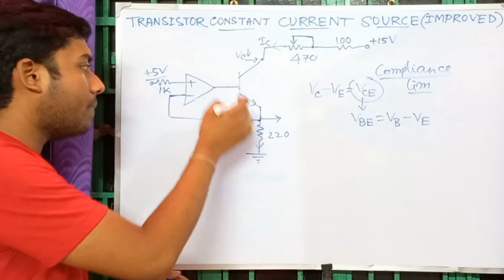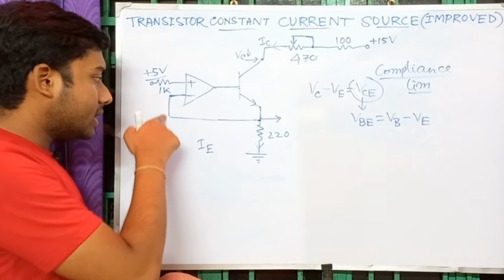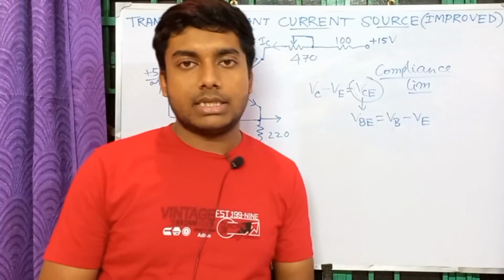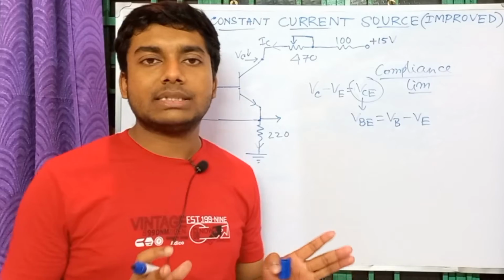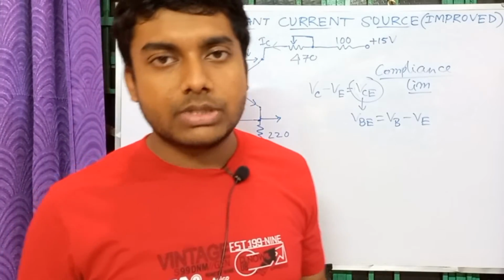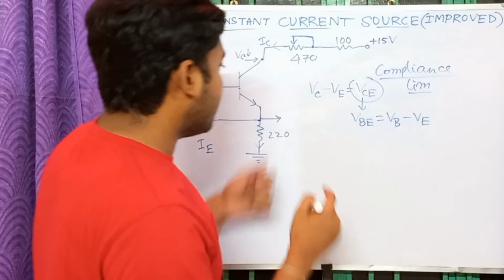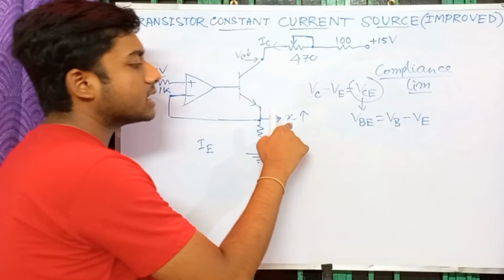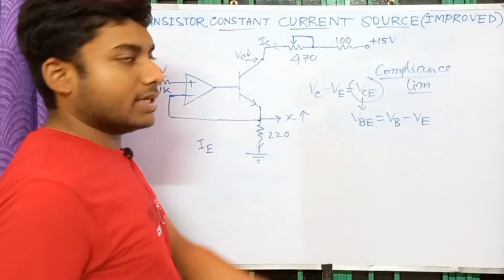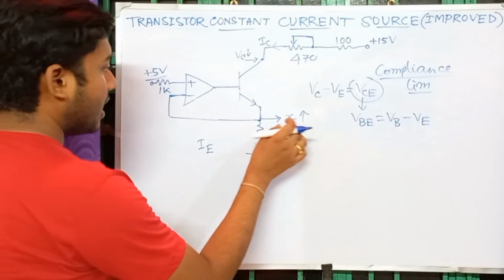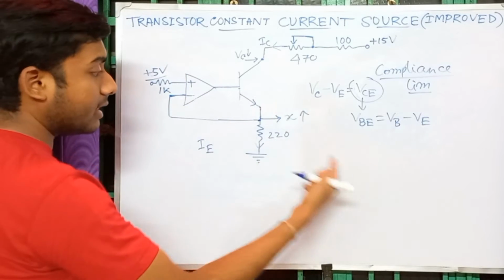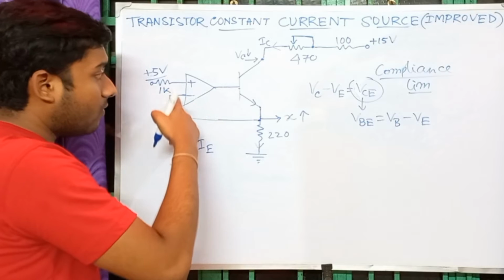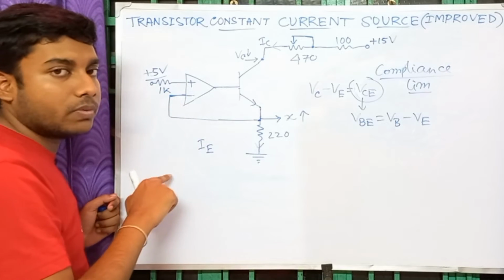How? Here it is an op-amp, right? Now this is the negative feedback of this op-amp. Is this negative feedback working properly in this circuit? Let us understand that first. To understand whether the feedback in an op-amp circuit is working or not, we have to do a thing. Suppose the voltage at this point is X. Now for any reason this is increasing. Then as this has increased, the voltage at the negative terminal will increase. That means the input voltage difference will be negative now.